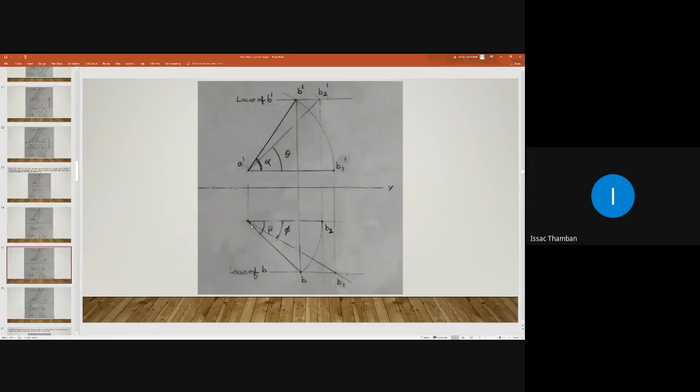So in this, you take your compass and take radius AB. Here A is missing, you have to put that. So take radius AB, small AB in your compass, and draw an arc and intersect this horizontal line at point B2. You will get this intersection here. You can name that point as B2. Making line AB parallel to VP.